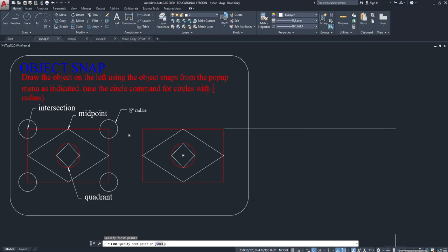Great. If I come down here and change this back to decimal, now you see ortho's turned on and I have 4.4030. That's decimal inches. All right, change this back to architectural. Nice visual illustration of what units we're drawing in. If I wanted to create a line that was 8 inches long right now,